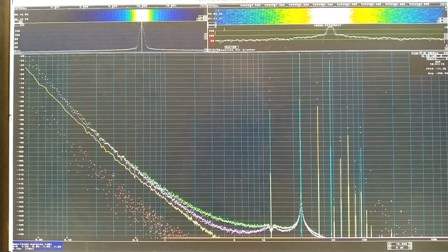I was using this oscillator as the reference oscillator in channel 1, as you have seen. Then the frequency was above 10 megahertz, 6.4 hertz above. I have increased the tuning capacitor to bring it on the other side of the 10 megahertz references, and that has reduced the power from 18 dBm to 13 dBm.